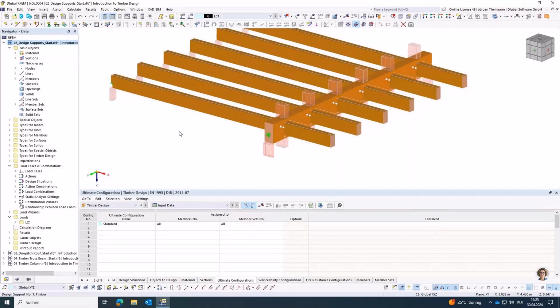So when you look at this rafter, you have a member set which goes from the wall mounting to that free end. But it's still supported at the place where it touches this girder. So this is now the exact length you need to consider for your deflection design.